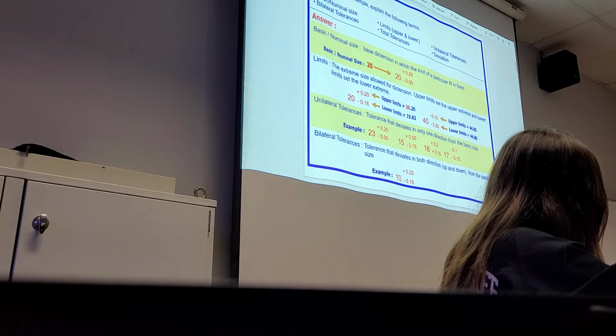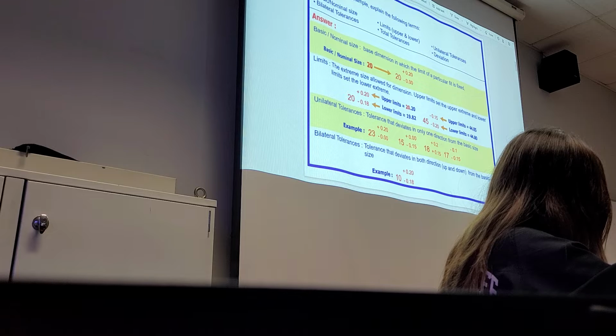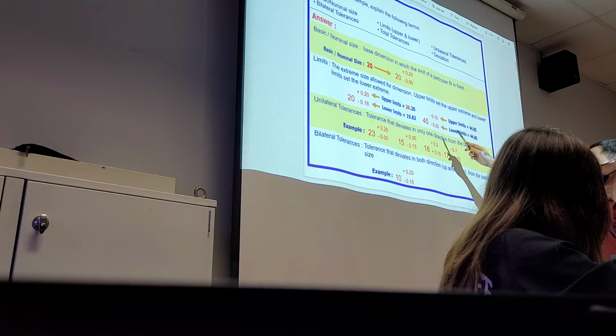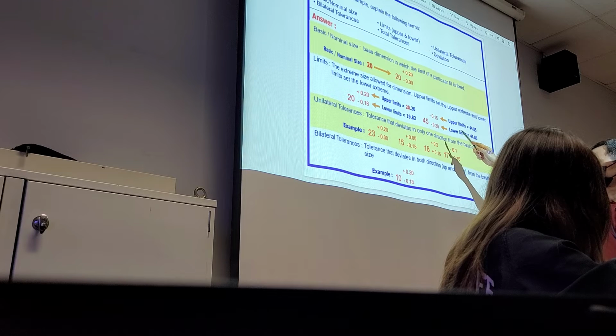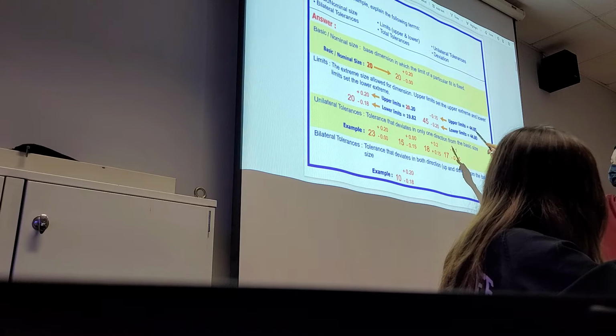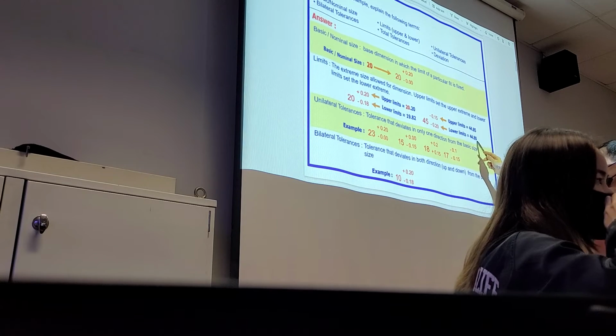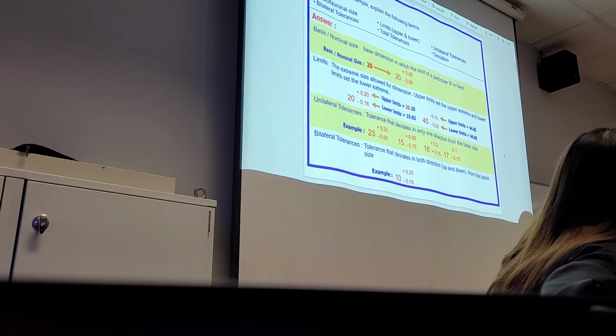So there's some terminology here. They say, okay, nominal size 20. When you create a CAD model, you use precisely 20. But when you come to manufacturing, you need to specify an upper limit and a lower limit. For example, this dimension, you have to follow 45 plus minus 0.15 minus 0.2. So actually the lower limit is 44.8, and the upper limit 44.85.